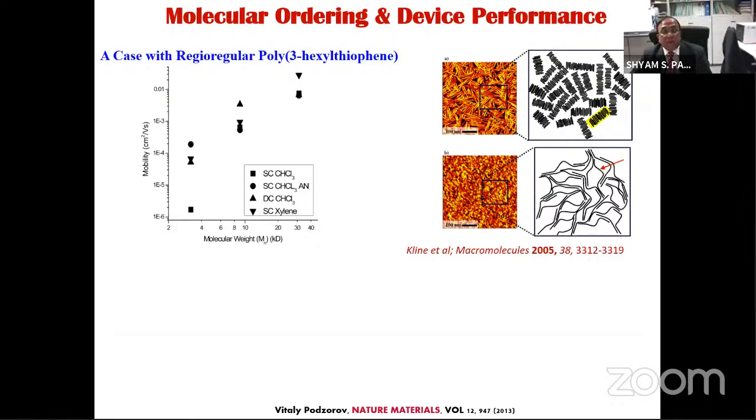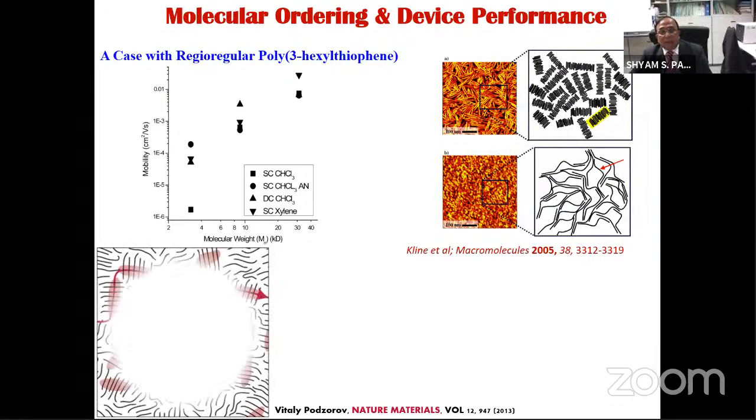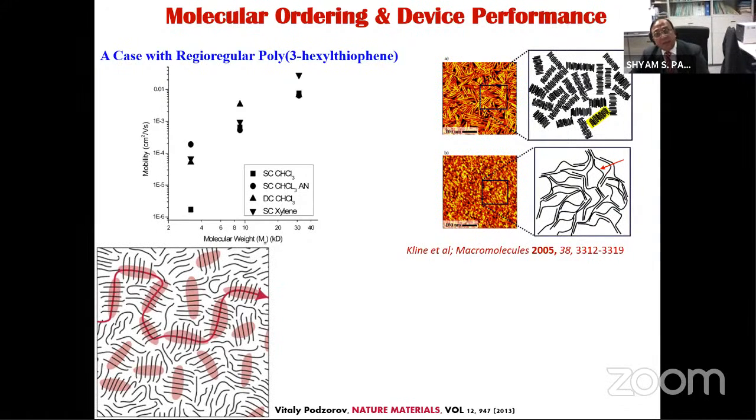It has been demonstrated that increasing the molecular weight, as you can see in this slide, increases the charge carrier mobility. Since they are quasi one-dimensional polymers, the charge transport is fastest intra-chain, followed by inter-chain hopping, and by self-aggregation they make a domain, then inter-domain hopping. And this controls the overall charge transport.